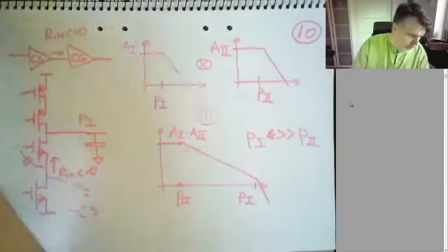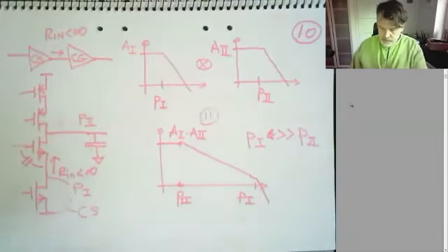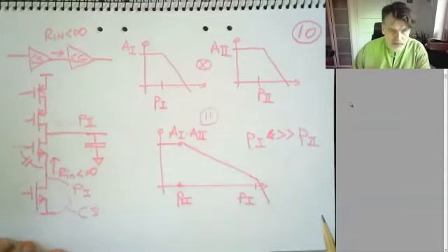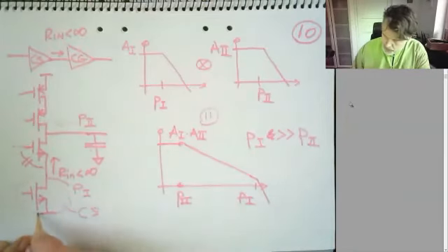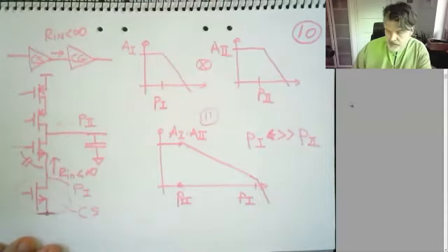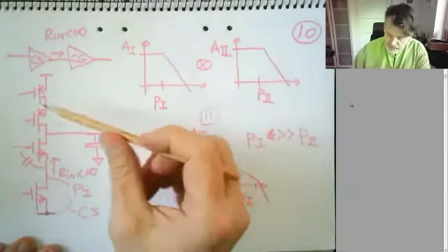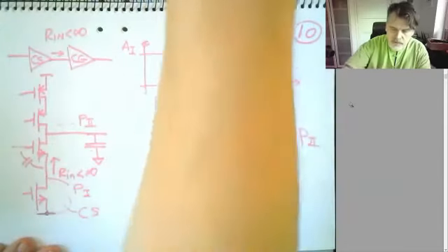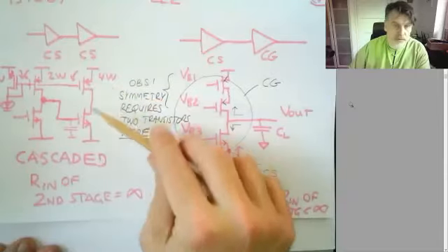However, as always with analog design, it has the issue of eating up the voltage range. We're not going to do many calculations here, but it's quite obvious. You have 4 transistors stacked on top of each other here, unlike the common source case where we have only 2 transistors.